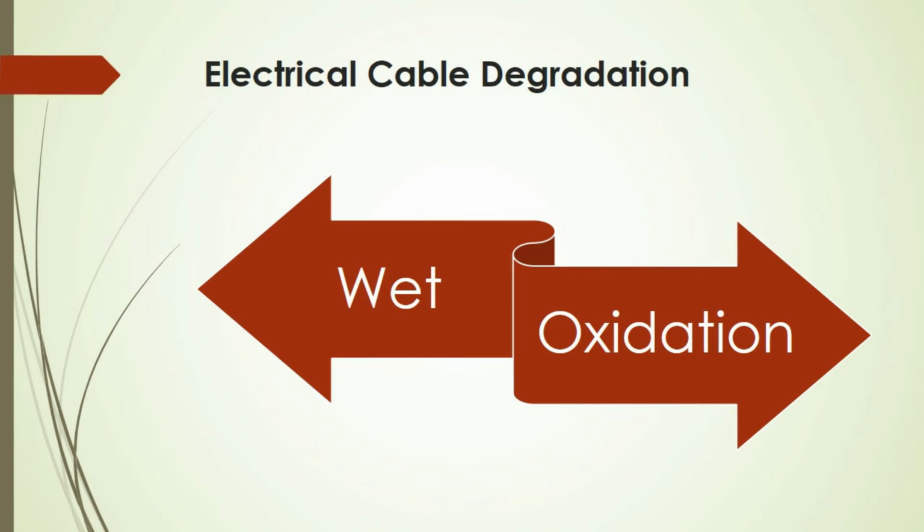Now, water and electrical treeing aren't the main causes of polymeric insulation degradation in electrical cables. Failure can also be caused by a complicated mix of processes. Radiation and heat stress can produce what we call dielectric oxidation, and the mechanical stress can cause fracture propagation across the dielectric owing to oxidation-induced embrittlement.